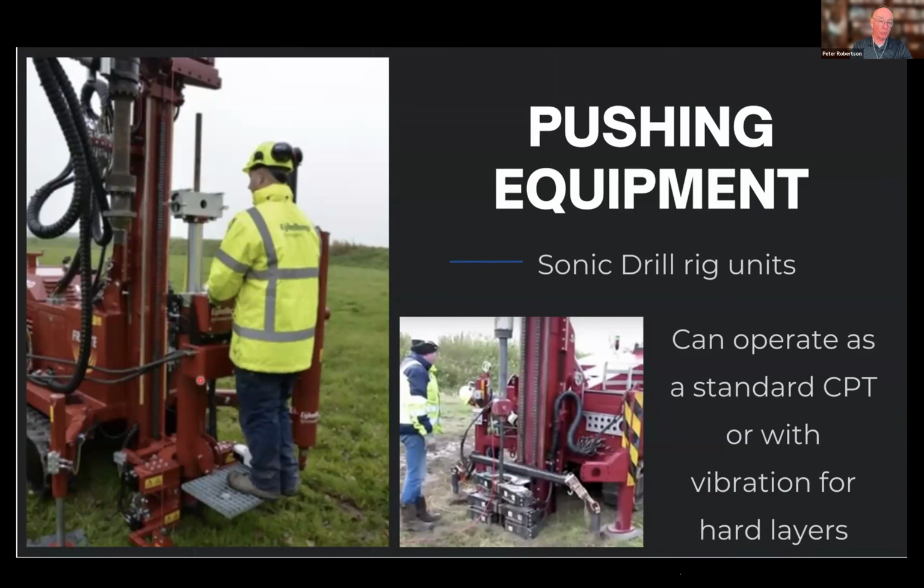And then after you've pushed the CPT, you can then swing it out of the way, and then you could do sonic drilling down adjacent to or over the top of where you just pushed the CPT. And then they also hit on the idea that if you slim down the electronics in the cone so that they weren't so sensitive, you could actually push it directly with the drill head of the sonic rig, turn the vibration off.